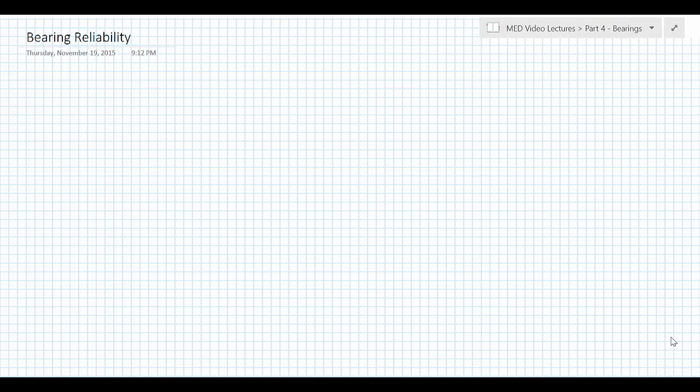Welcome back. In this video, we're going to talk about how to select a bearing at a different reliability than the manufacturer's provided reliability. Recall when we talked about bearings, we talked about how they fail stochastically, which means we don't necessarily know when a particular bearing is going to fail. Instead, we have a prediction based on the probability of a failure occurring in that lot. So what we have is a number of failures for that type of bearing over time.